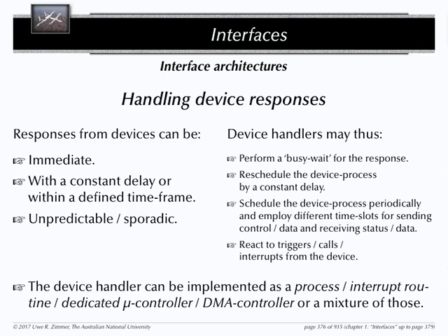All these questions about how long do you wait, or do you wait to be called back when something happens, is something which you have to address on a daily basis if you work in an embedded environment or any kind of a physically connected system for that matter. Usually this is taken away from you by the operating system if you work on your desktop machines. Because if you do I/O there, what actually happens from your user program perspective if you do I/O?